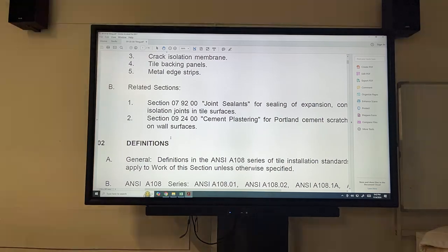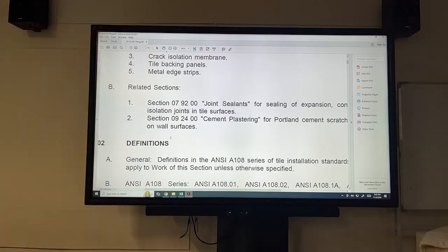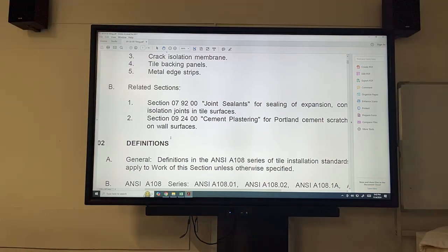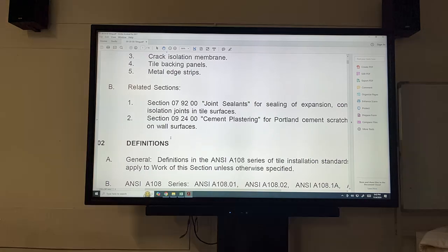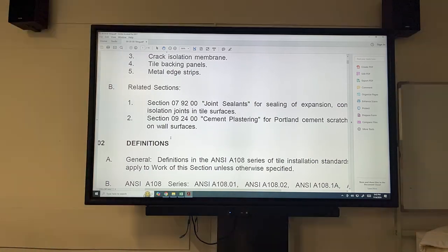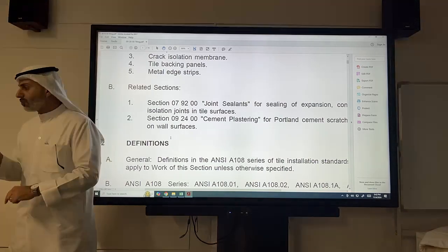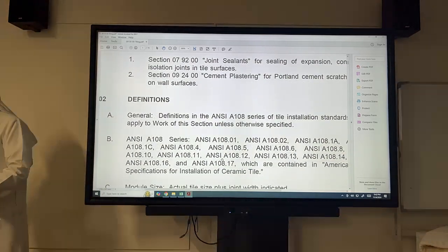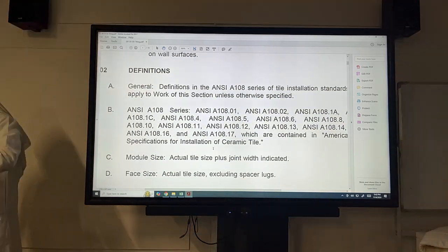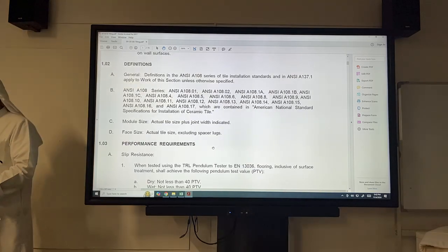Sometimes they're left like that, and if we need to be waterproof, then this water is going to just go inside. But usually they're filled up. But that tells you how big, for example, every two meters, you have to put an expansion joint, what to fill it with. So it's telling you also what else it's related to. And then that's in another section, not just under tiling.